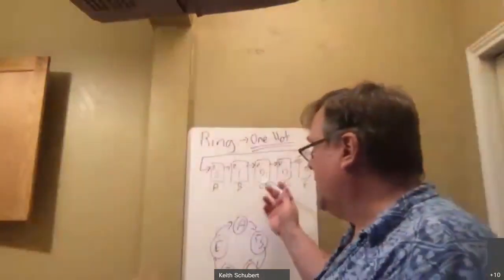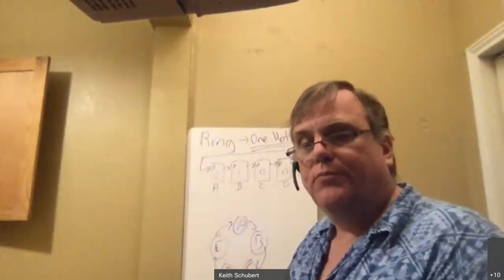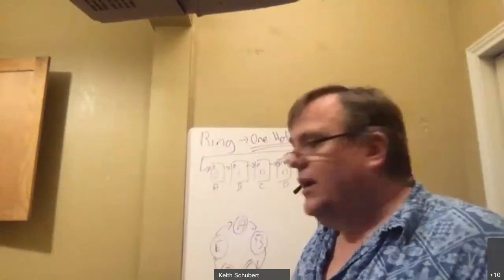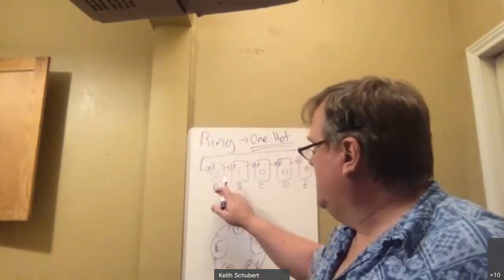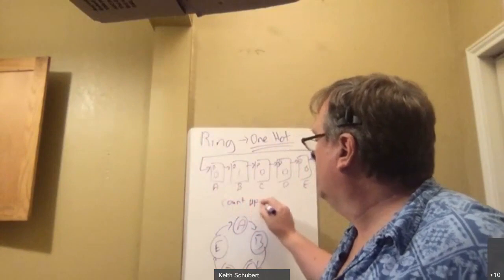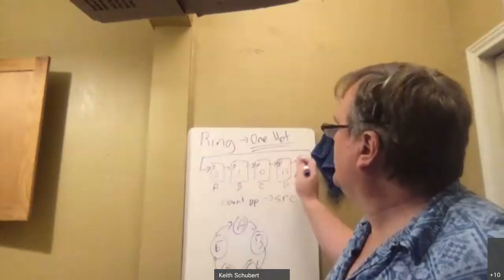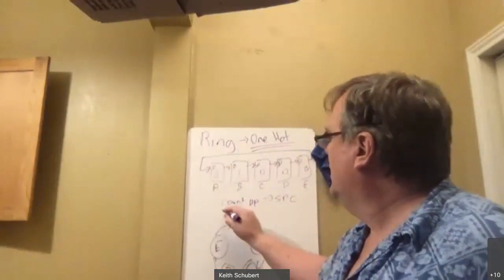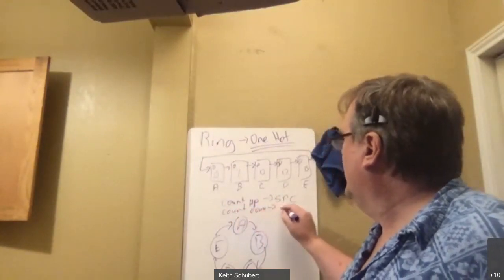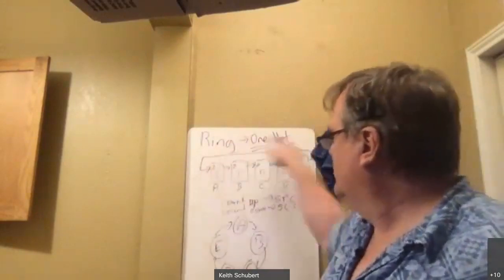It's a very simple counter to build, so there's not a lot to this other than understanding its use. It's obvious that as you keep shifting, it'll walk through the states. Count up is a shift right. Shift right circulant is the technical name because it goes around in circles. Counting down is shift left circulant. You go the opposite direction and it circles around the other way.